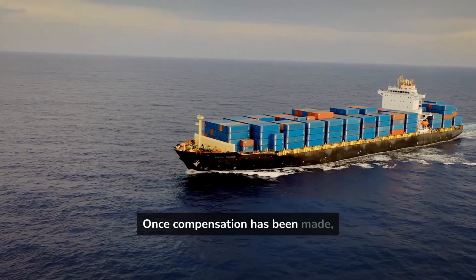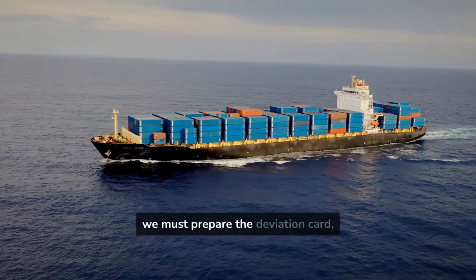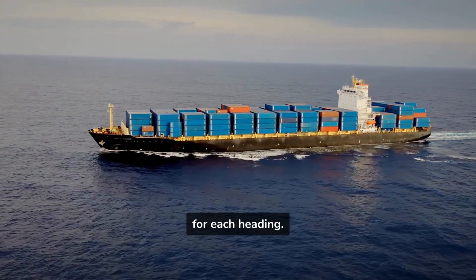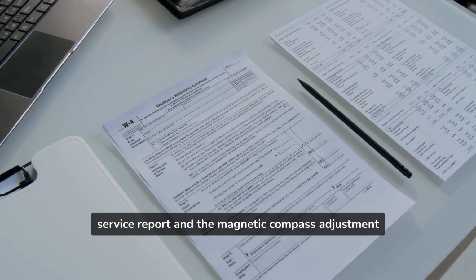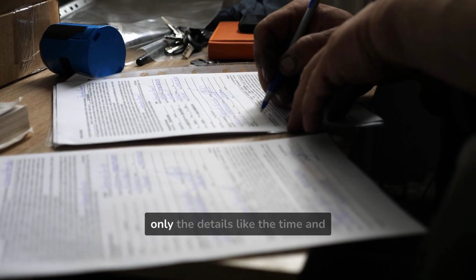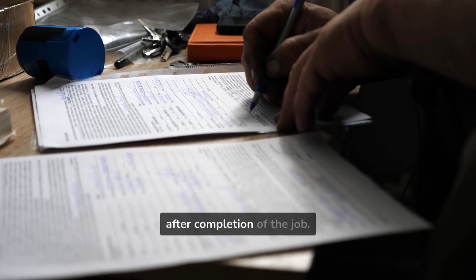Once compensation has been made, it is impossible to eliminate the deviation completely. Therefore, we must prepare the deviation card, a document that indicates the residual error for each heading. It is of paramount importance to have the documents, service report, and the magnetic compass adjustment certificate ready to be handed over to the captain. Only details like the time and the deviation values, of course, will be missing and will be introduced after completion of the job.